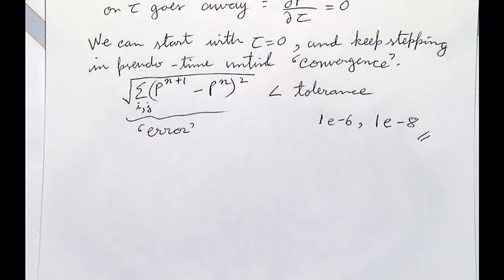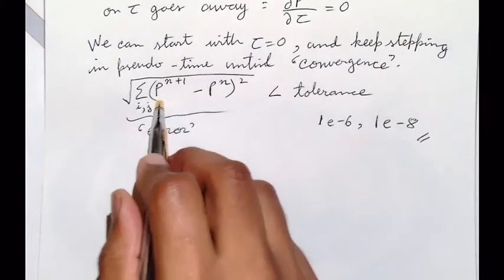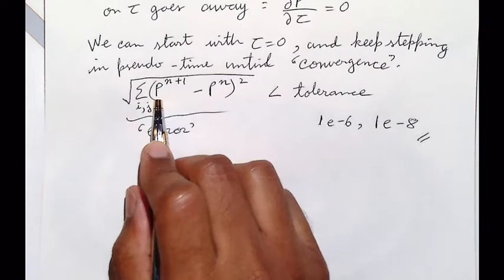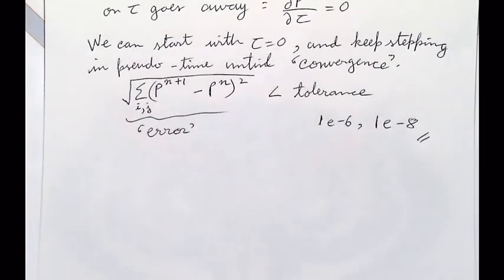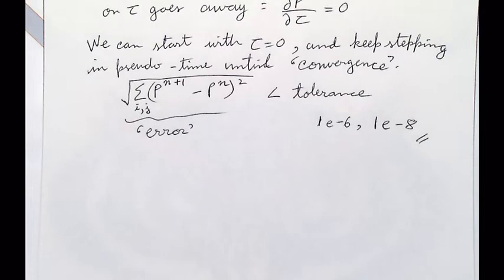Bernoulli equation, for example. The what? Bernoulli equation for incompressible flow. Okay, so if I give you the pressure, how would you do that? I mean, Bernoulli equation is P naught equal P static plus half rho V squared, right? And there is a V squared. You cannot get V and U components individually. So you cannot get the velocity field that way. Makes sense? We don't have enough information.